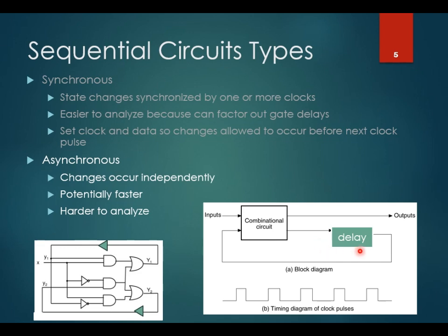Instead of flip-flop, it has an element called delay elements. This one is very important because the delay element is to adjust to ensure the proper timing and synchronization of the signal to prevent the hazards such as the race condition, glitches, or even the metastability situation. Looking at the gate level, the delay element can be realized by adding the buffers.